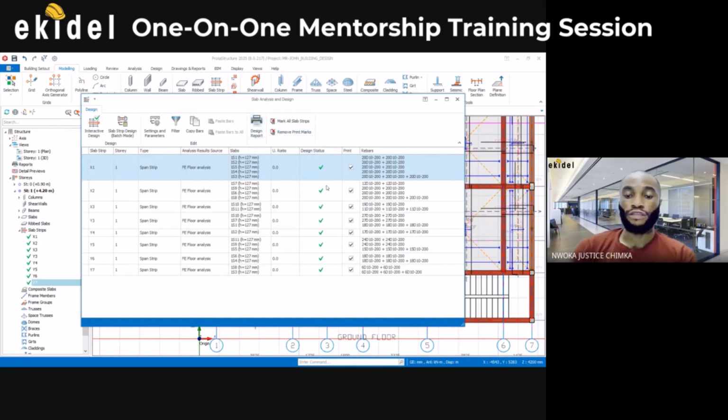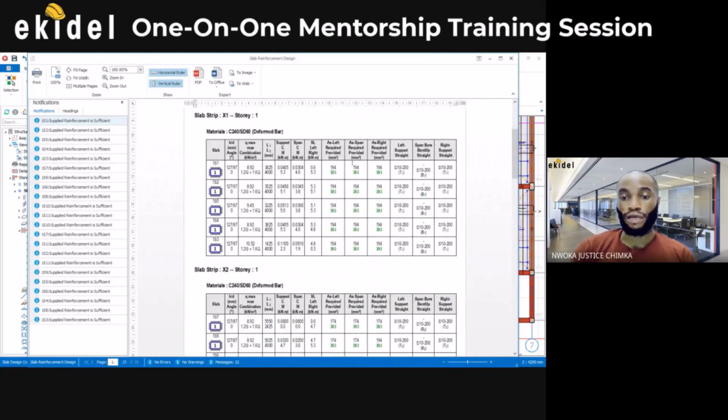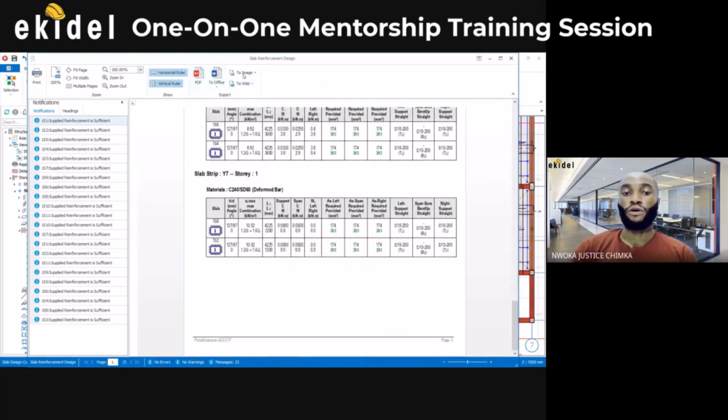You can see first everything is okay here, else you'll be seeing failure. You can see the spacings of each of the panels and all that. But you can generate this report from here by clicking here, design reports, and then just hold on for a while. It doesn't take much time. So, okay, I think it's already done. Correct. So you can see the slab design report now for each of the panels. I can choose to do PDF or Word, but let me just cancel that.